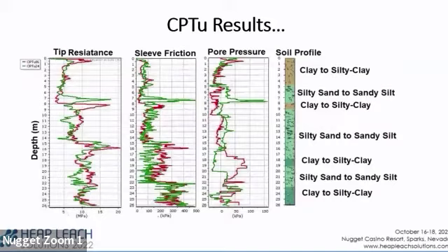So you get a graph, and it's called the state factor. And if your curves are on one side, you're okay. And if it's on another, you're not. And as a case in point, a few weeks before the Fundão Dam failed, they had a CPT rig on it. And because I was part of the review team, I got to look at all that data. Half of the profile depth of every hole was on the wrong side of that line. That predictive tool really works.